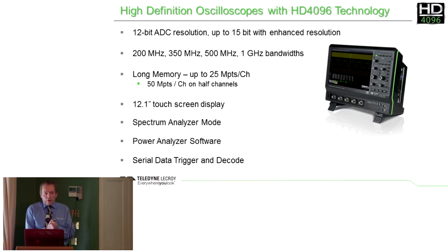Why only 1 gigahertz? Why don't we do it at 4 gigahertz or 20 gigahertz? Because actually the A to D technology to do 12 bits is very difficult to do, and you have to have your A to D running that much quicker. And at the moment we don't have A to Ds which are running at 40 gigahertz or 80 gigahertz. So at the moment we're limited very much to 1 gigahertz bandwidth. But all of the low frequency type measurements, and there's an awful lot of them, so 1 gigahertz and below, have the advantage of having 12-bit technology available.